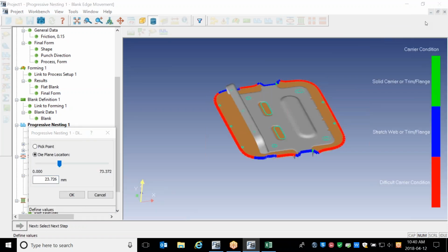Right, absolutely. So what we're looking at here is the die plane. It just happens to be that in this case, my tip axis and my global coordinate systems line up. The way the software works is when you bring in your part in whatever orientation, typically in car position, we use the global z-axis as your default for tip. Then when you define your local coordinate system, our tipping direction or punch direction, we create a new local coordinate system that uses z as your tip direction. So that's what that yellow arrow is.